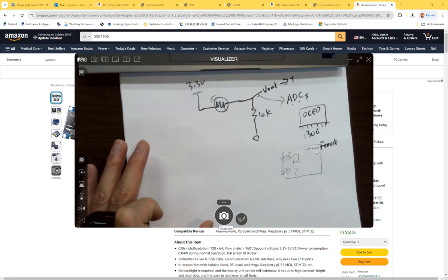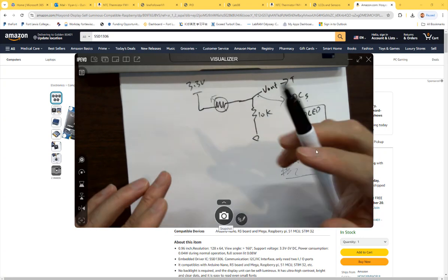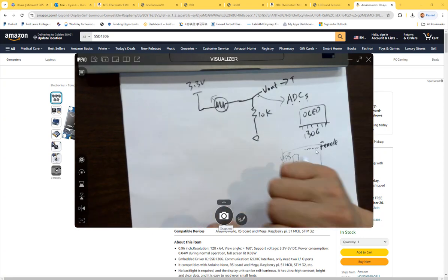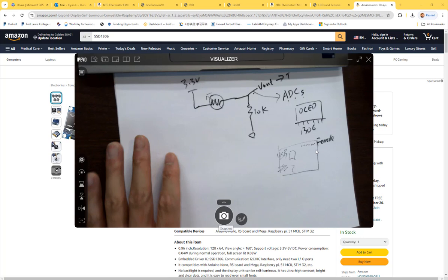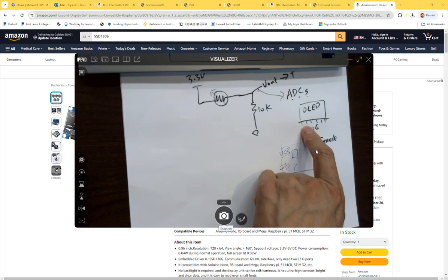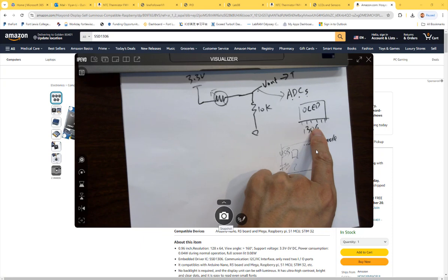Did you know if SparkFun had one of those OLED modules and you just drag in the library? I didn't see it, because SparkFun probably doesn't work with PIC too much. I saw that it fits in a breadboard, so whatever the distance between each of those pins would be the same that you would use. Yeah, these pins are almost the same. It's standard header pins. These are all universal header pin distance. So for the display, you can use that with the PIC. Yeah, you can use this one.